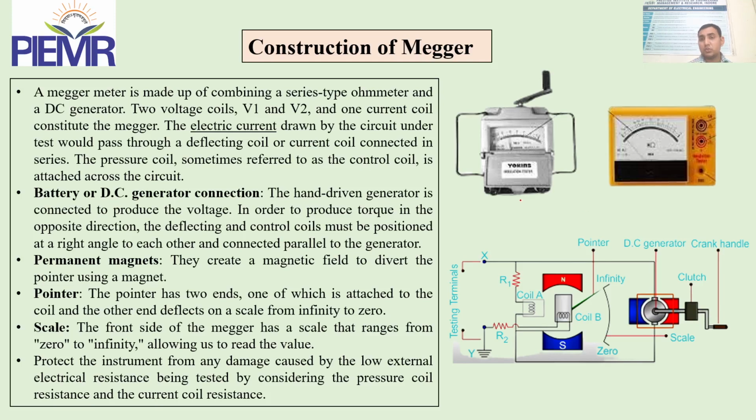Before 2015 we used this crank lever type megger in measurement apparatus and industry, but today we use electronic measurement devices, which are battery operated versions where we put only batteries and they show the resistance. We do not need a crank lever to generate thousands of volts. It manages its own voltage using DC to DC converter devices.